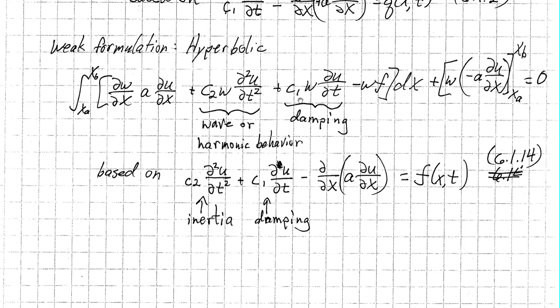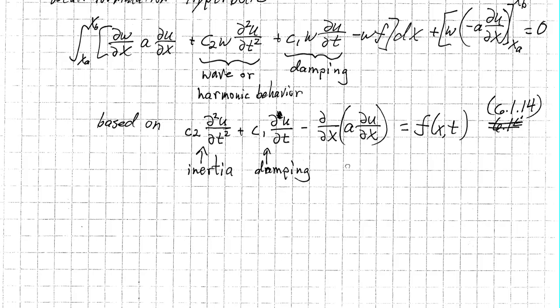This is damping. So these are losses. Anytime C1, your damping coefficient, is not 0, you're going to generate losses. When this term goes to 0, it's a fully conserved system. Energy is going between kinetic and stored elastic energy. And over here is your boundary condition. So if you have a load on the end, that's where this gets implemented or introduced.